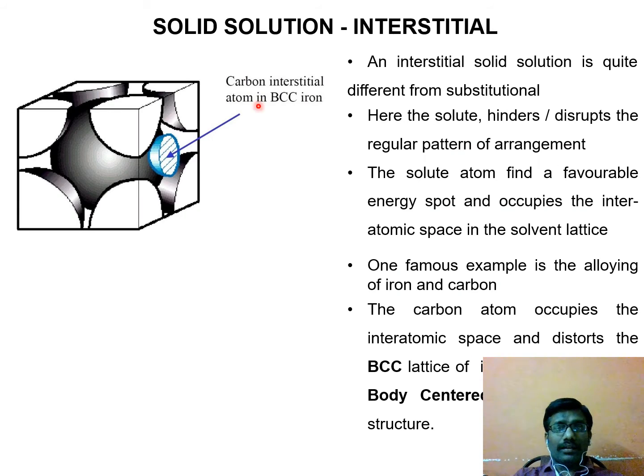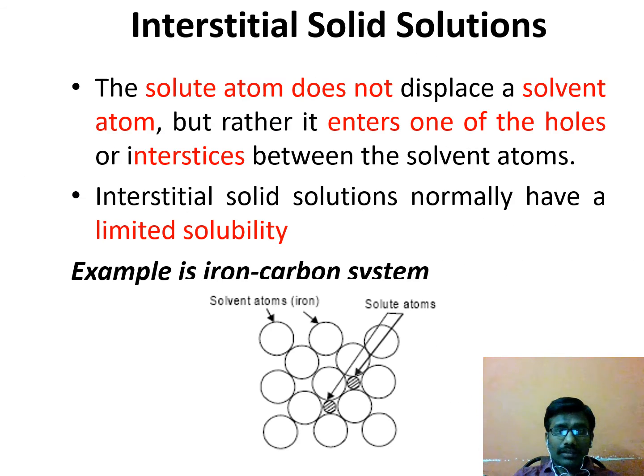Now we can see the interstitial solid solution. In an interstitial solid solution, the solute atoms occupy the voids or spaces in the crystal structure. These are all the solvent atoms, and the solute atoms occupy the gaps or voids in the crystal structure. So this is called interstitial solid solution.